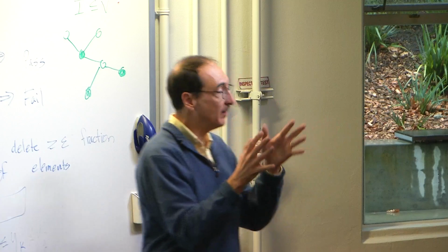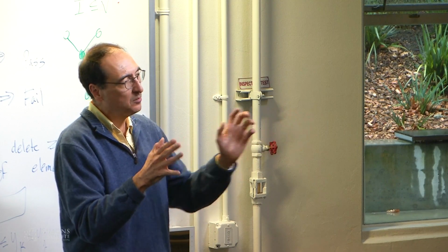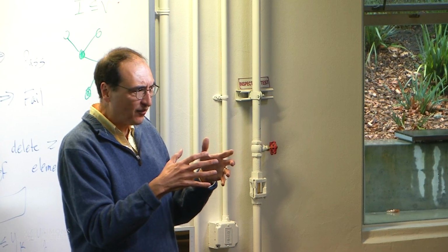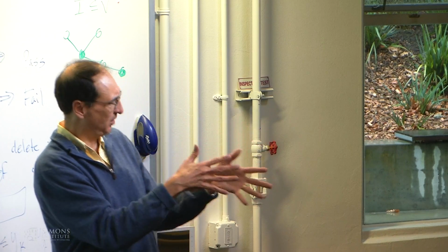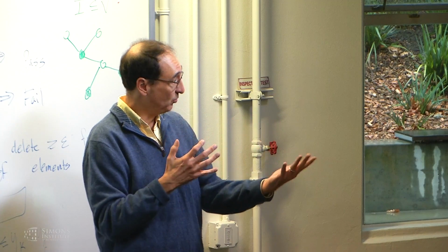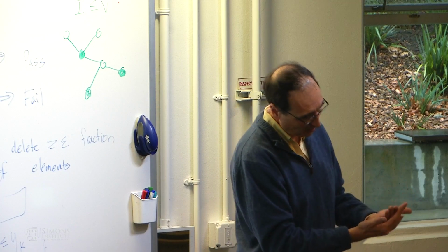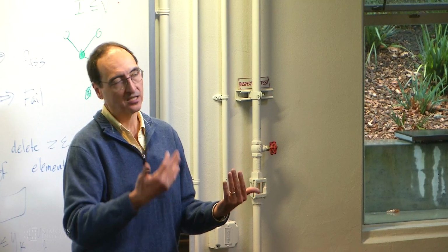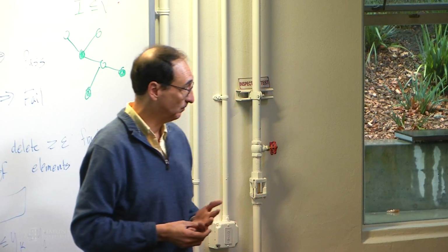So there's a fundamental trade-off that we understand, and it's the reason that people don't do eigenvalue placement so often, because that trade-off is hidden. It's in there. I can pick the eigenvalues and then tell you how bad it was, and you say, oh, that's not very good, let me pick a new one. The linear quadratic regulator lets me specify that explicitly. I can tell you what trade-off between error and input you want. And the linear quadratic Gaussian problem, LQG, allows me to also estimate the effects of noise and disturbances in a stochastic setting, so we can put that in there as well.